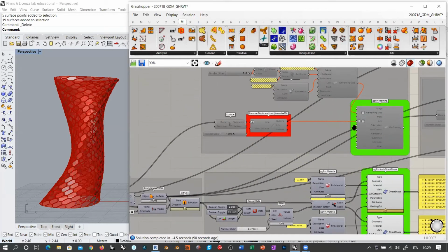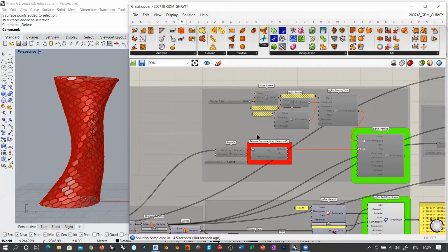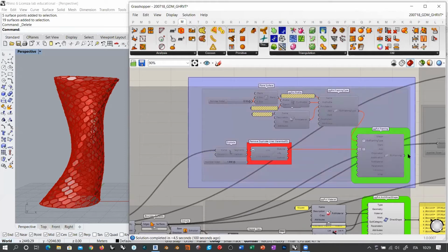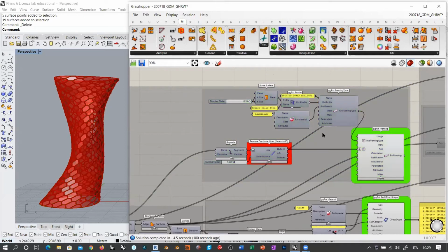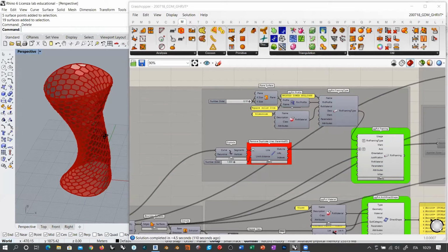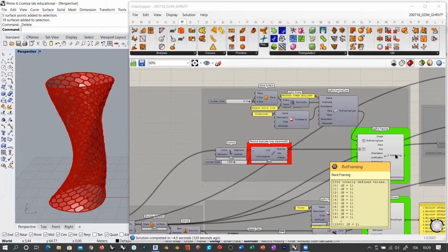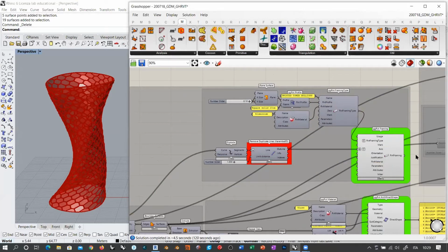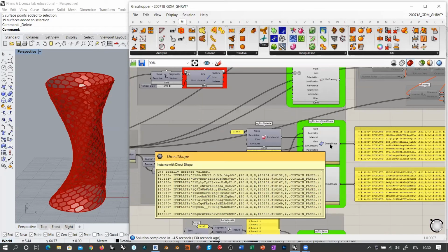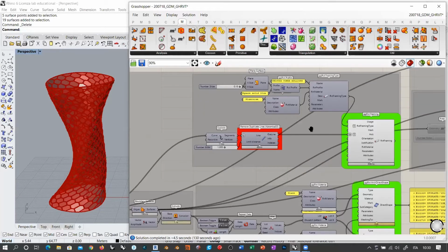As regards the structure of this facade, these are the mullions, which, by the way, are turned off because there are quite a lot of mullions. I recommend that you export them only when you are sure that everything is going to remain more or less like the final version, because importing these as they are, 1,500 mullions, is going to take forever in Revit to complete the import process. Not the panels themselves. The panels are not that many, more or less 500. So it's not that time consuming, but the mullions, yes.